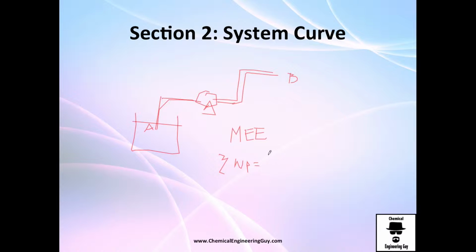or the pump requirement, and all the data, for example, change in height, the velocity head, friction loss, and the pressure head. All these equivalent will give you the amount of energy requirement for this pump. And this is what we're going to do. This is the system head.